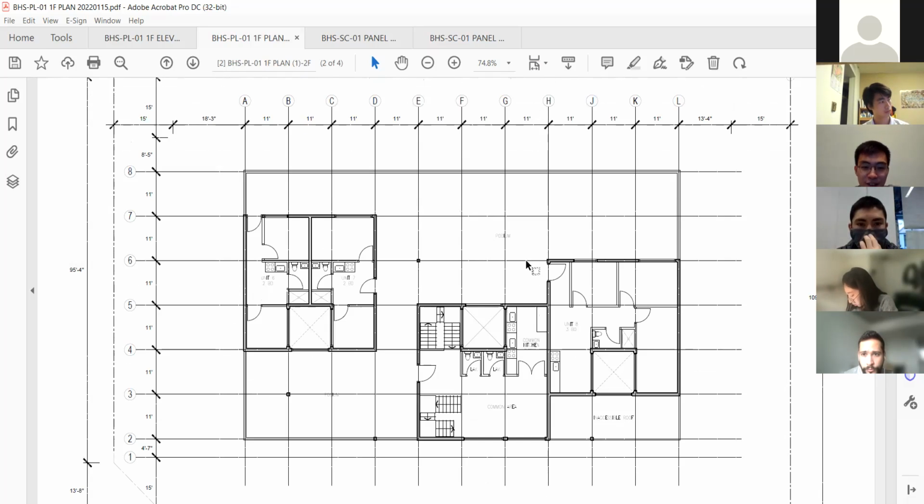So no, I don't think the insulation is the problem. You just insulate where there's a building, but the transition between the building and the deck is going to have to be with the same outer material that people are walking on, right? Yes. So have you guys thought about that aesthetically? Because it's obviously possible, but you're going to have to have a waterproof roof material.